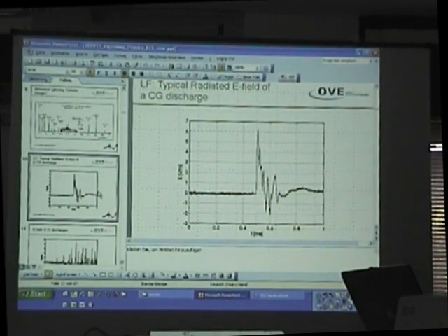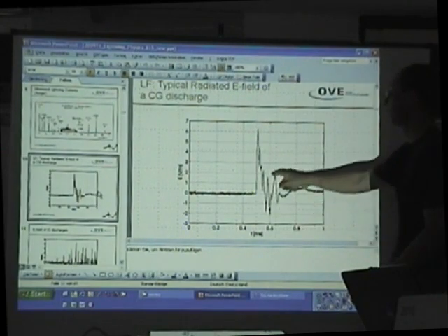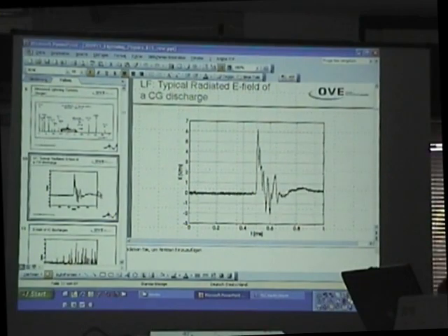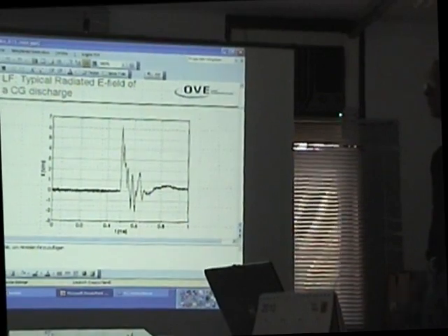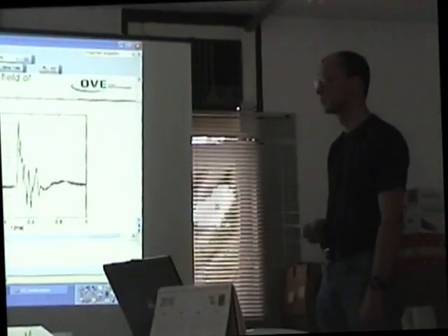I think it's a natural oscillation of the curve, but I think it's not reproduced up to now by models. Did you hear the discussion in the session? They tried also, as one of the criteria of a good return stroke model, that it shows this zero crossing after about 50 microseconds. They don't succeed to do it, at least for close lightning.